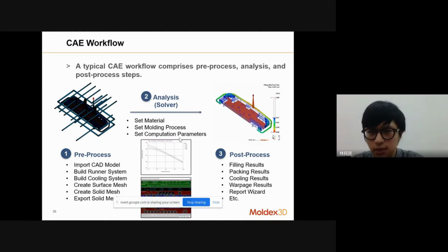And the warpage result, actually warpage is the next step of the manufacturing. With warpage, we need to check whether it will become like a smile face or a crying face. If the warpage deformation is too serious, we also have to think about the fiber orientation inside, and how we can set the orientation of the fiber to solve the problem.